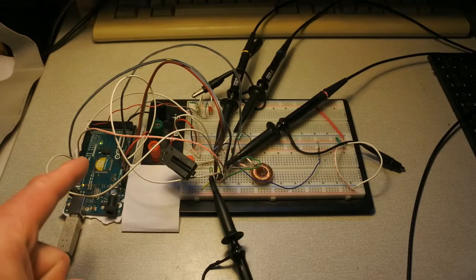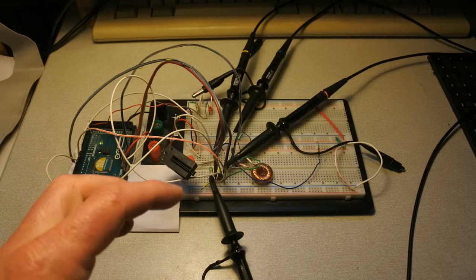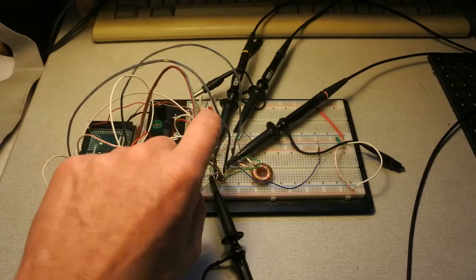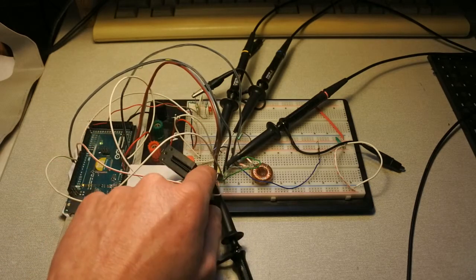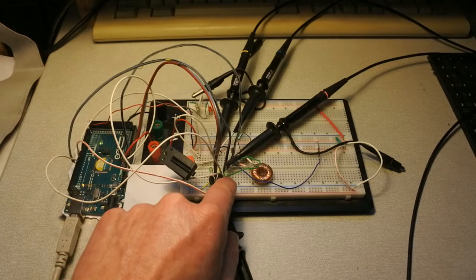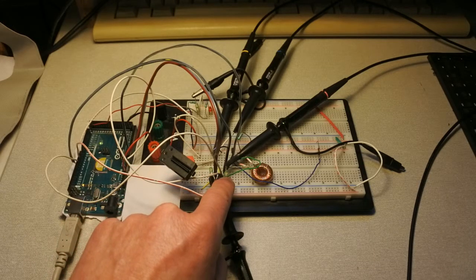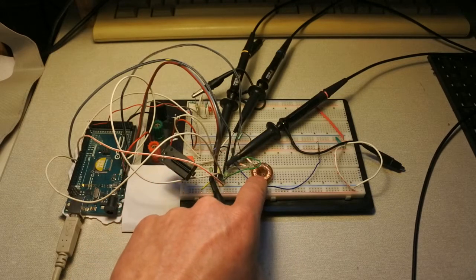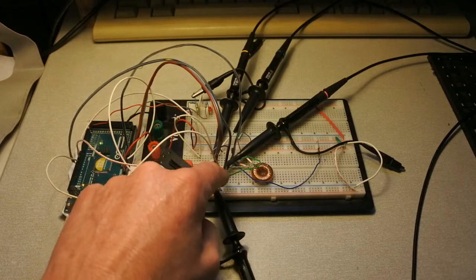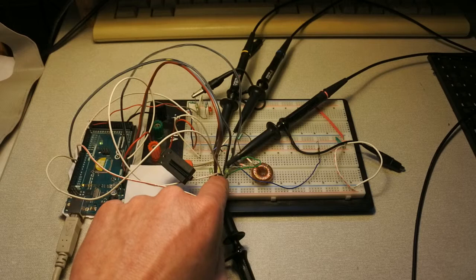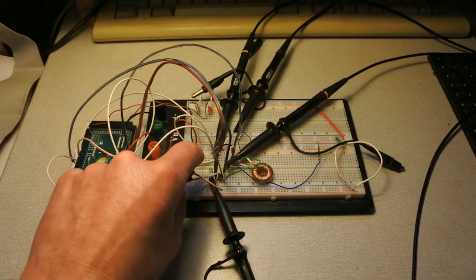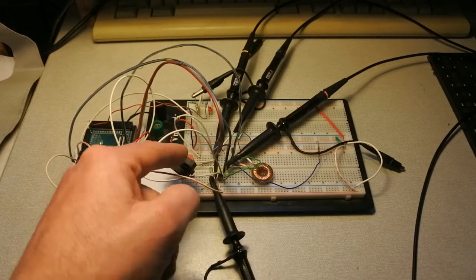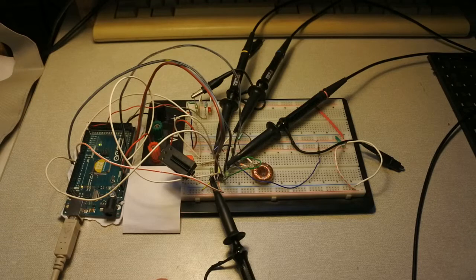The objective is to use pulse modulation to send a signal over this circuit with a transistor, which is here, and two LEDs, where this LED signals voltage from this circuit with the inductor, and this one just the voltage over the transistor. The switch just blocks or passes signal.